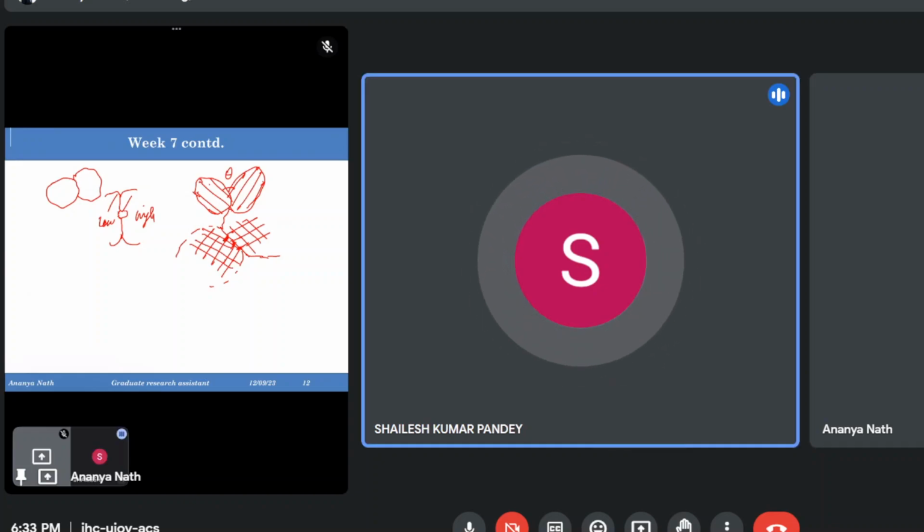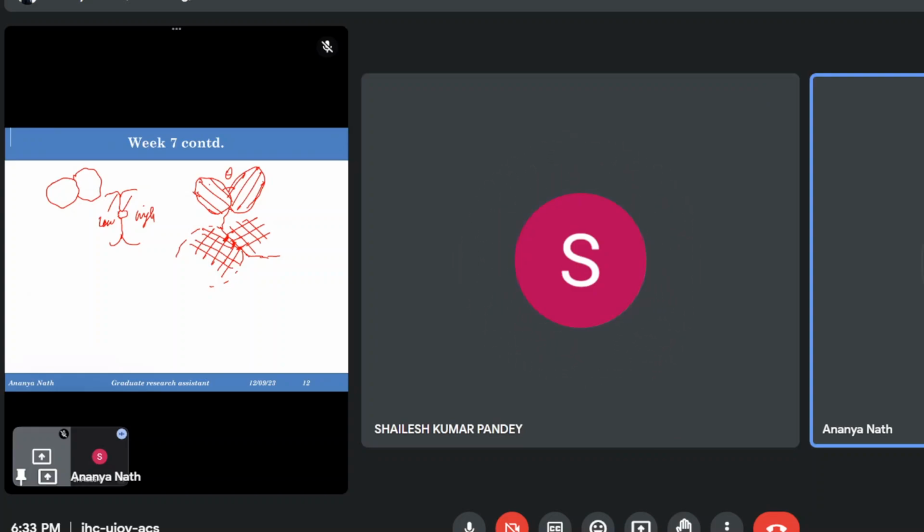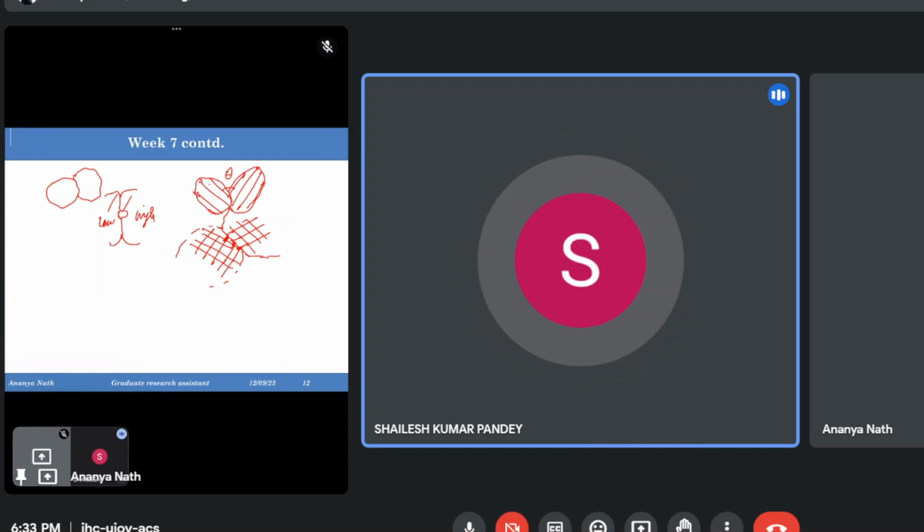Yes, ma'am, we discussed in the previous class that in a micro shear band, the two low angle configuration dislocations are interacting. So if they are interacting, at the junction they are making the bond, as you said in this diagram. So is it possible to have equiaxial grains? Equiaxial means the direction of all the lattices, they prefer some orientations in any direction. Is it possible to have equiaxial grains, because they are making a high angle boundary if these two low angle configurations get interacted?